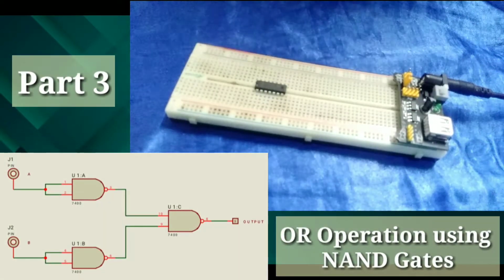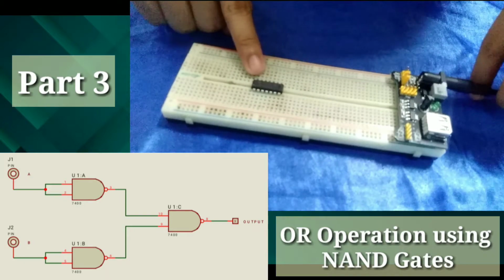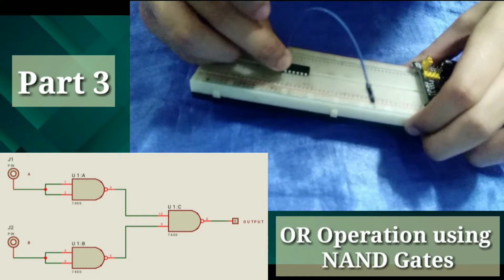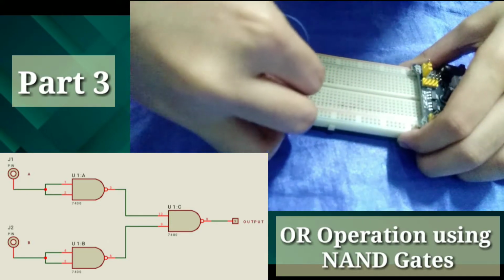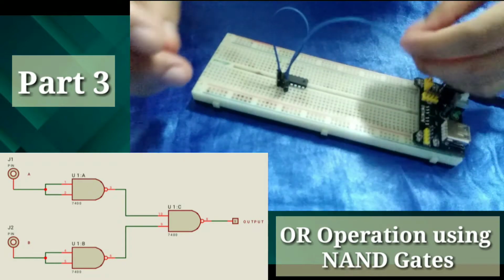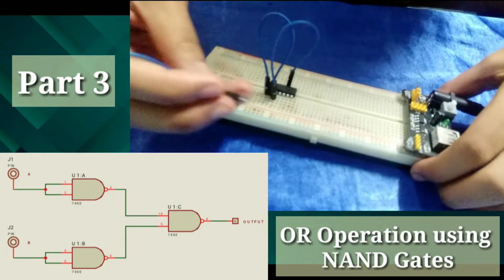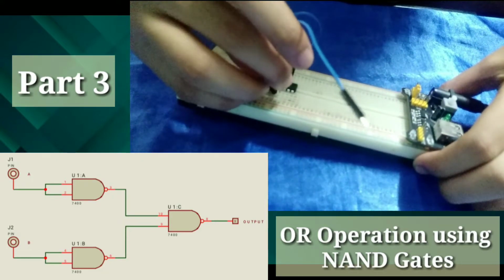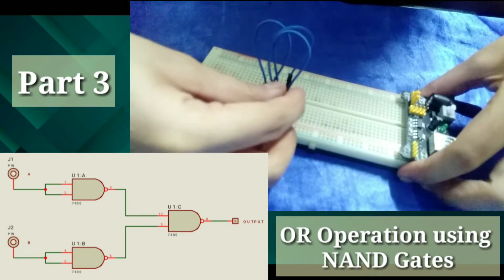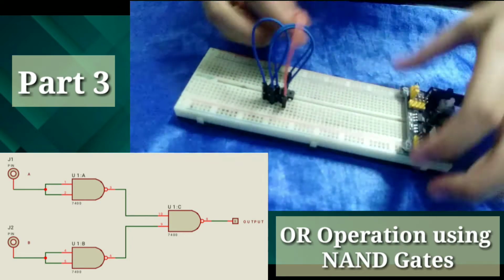Now, for our part 3, or operation using NAND gates, we will be needing a 7400 IC for the connection. Let's first connect pins 1 and 2 of the IC. Now, connect natin yung pin 3 to 10. So this is 8, 9, and 10. Now, let's connect pin 4 and pin 5. Now, connect pin 6 to pin number 9.